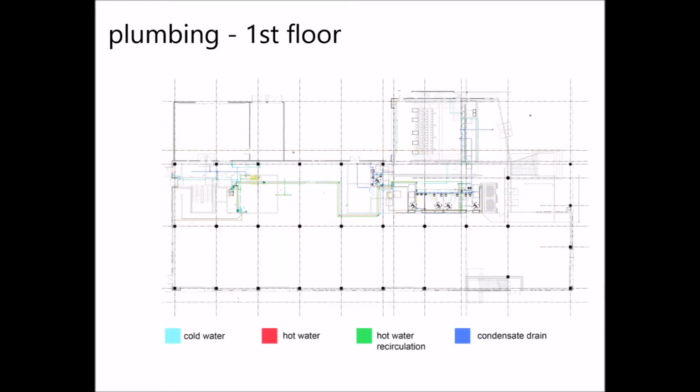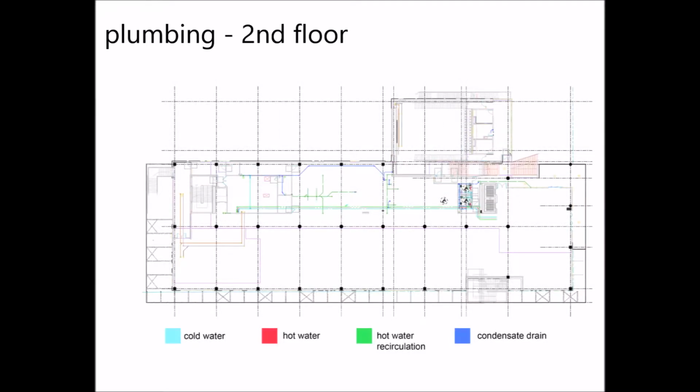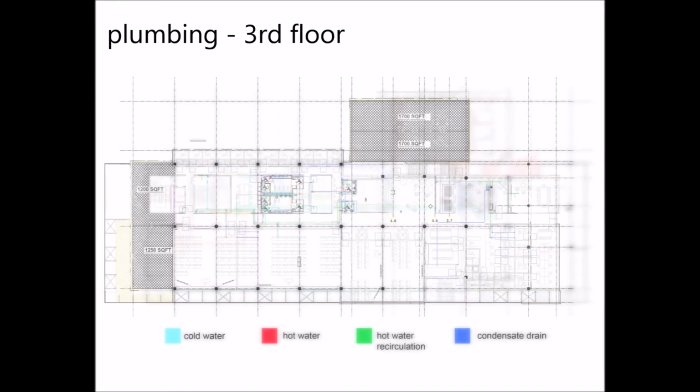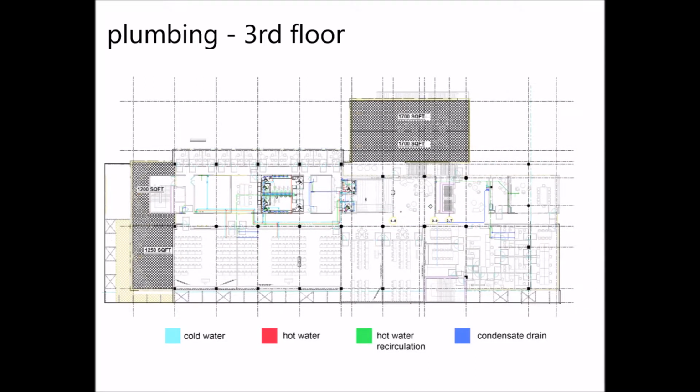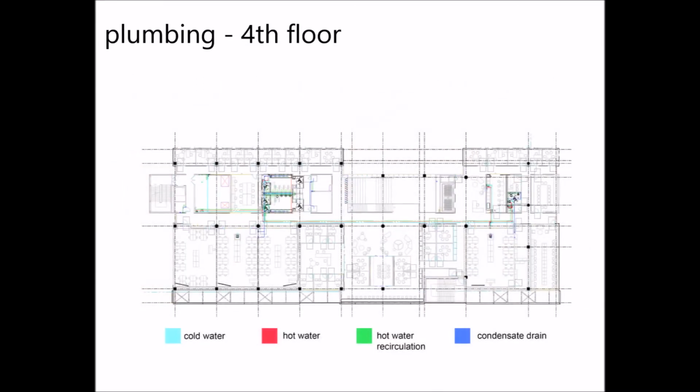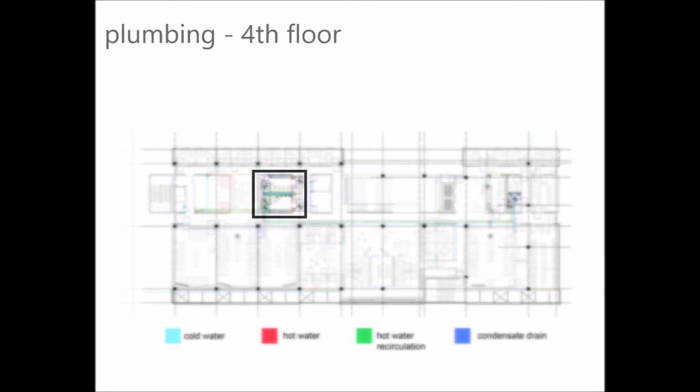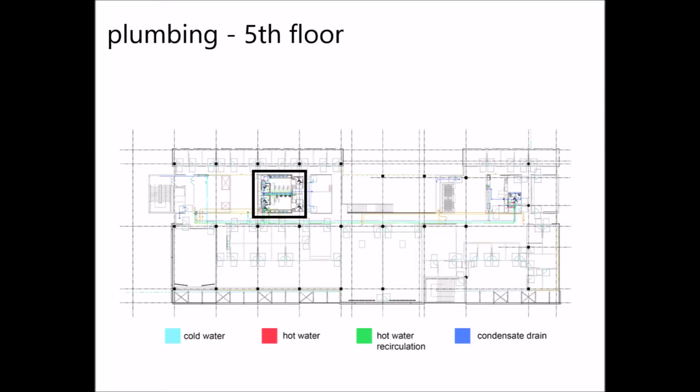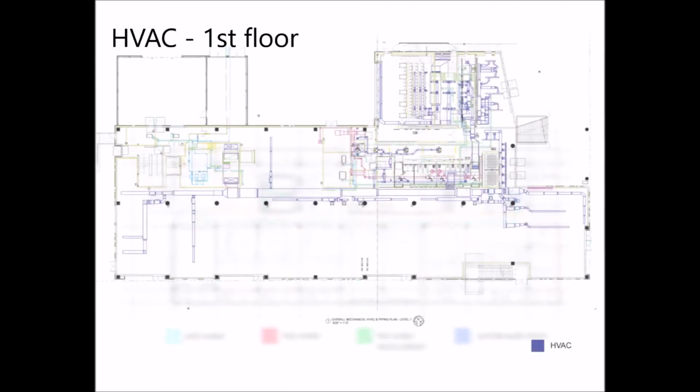We wanted to focus on understanding the 4 main plumbing lines that went throughout the building on each floor. The 4 pipelines tend to be placed along the same parallel core. It is clear to see that they stay in a similar area and cut through the ceiling from room to room. On each level, the main bathroom stays on the west side of the building, meaning that there is a solid plumbing wall that runs vertically up throughout all 5 levels of the space.